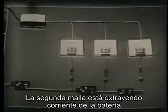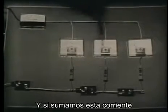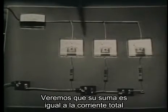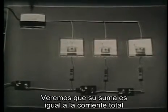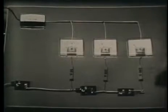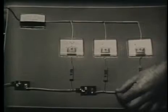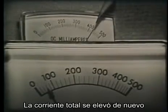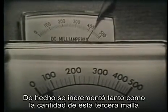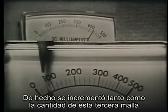This second branch is now drawing current from the battery. And if we add this current and this current, we'd find that their sum is equal to total current. Well, let's see what happens when we add this third branch. Closing this switch, watch total current. Total current increased again. In fact, it increased by the same amount as the current through this third branch.